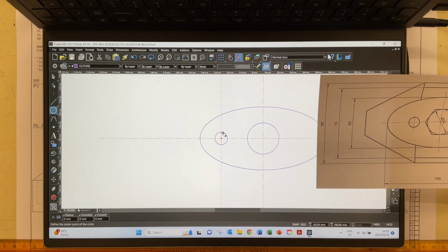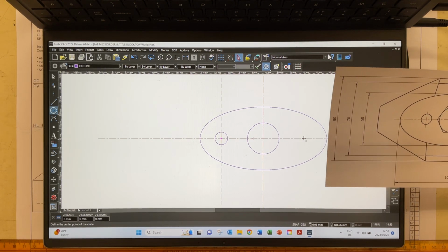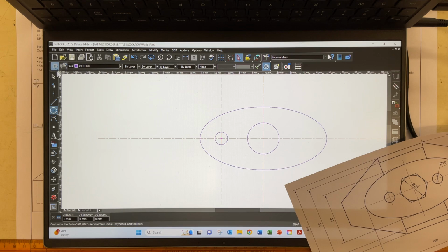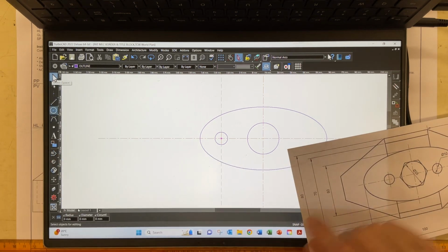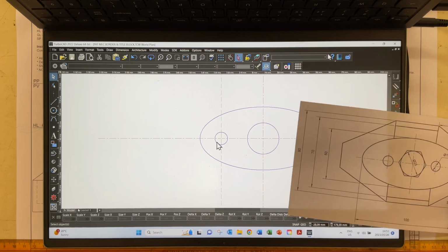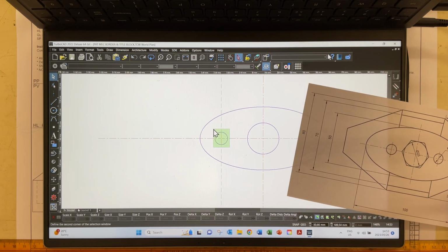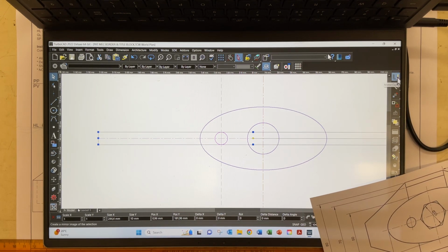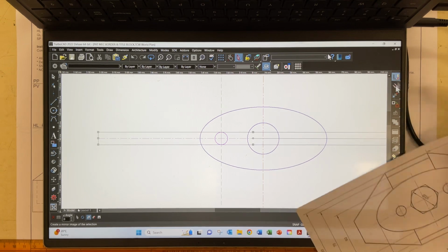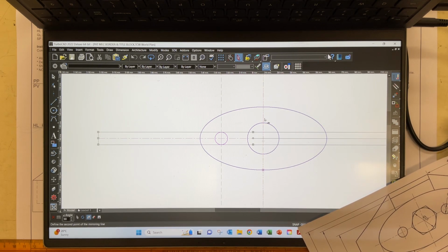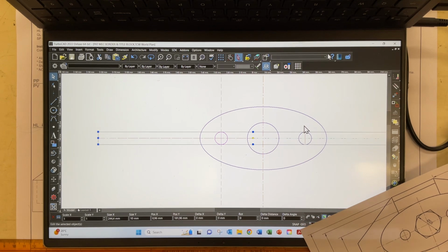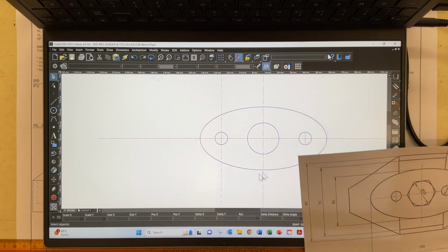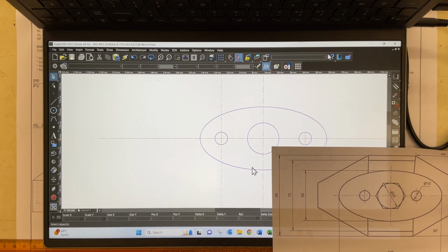Now I want to have that same circle drawn on this side over here. If you remember from the last time, I said you could select that, get that little select arrow up there, click on that, click on the select arrow, select that little circle over there, okay, and we are going to mirror that around the axis. Click the mirror thing up there, and you're going to click over there, and there we go, we've got our mirrored circle.